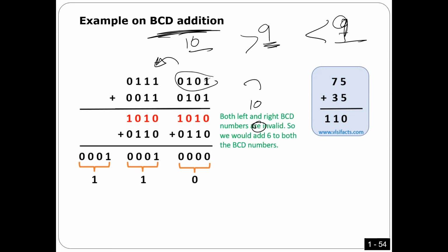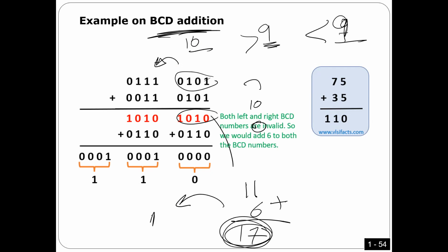So again, the idea is that in decimal, I'm going to have a carry every time the number is greater than 9. But the way I do it here, you are going to generate a carry every 16, right? So if this number is 11, I have to add 6. Once you add 6, it becomes 17. Out of the 17, as I told you, every 16 is going to move as 1. So the result will become 1 here. Is that difficult? You understand what I'm saying?